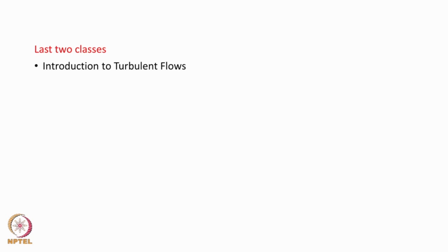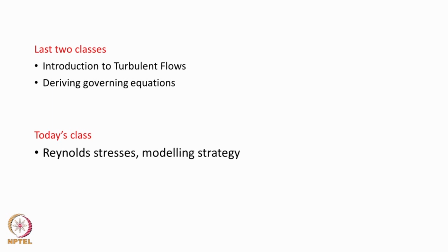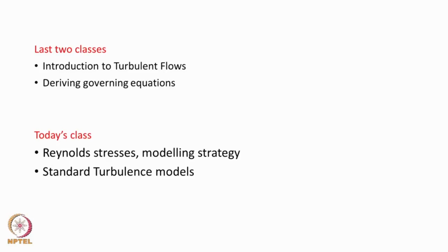In the last two classes we talked about turbulent flow characteristics, then we learned how to derive governing equations for turbulent flows. In today's class we will continue that exercise, we will try to understand more about Reynolds stresses, how to model the Reynolds stresses and different approaches available to model these Reynolds stresses. Then we will see whether we can do something about introducing standard turbulence models.